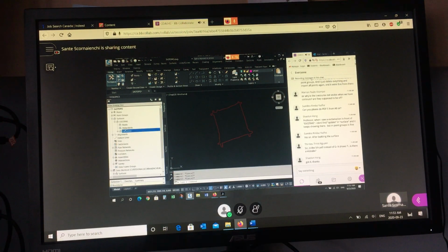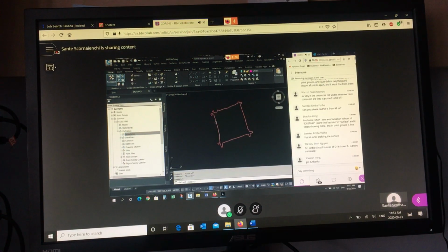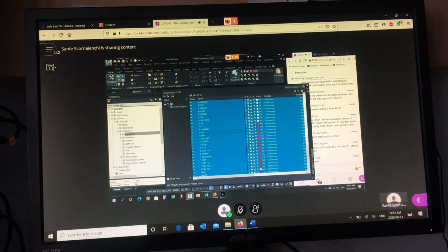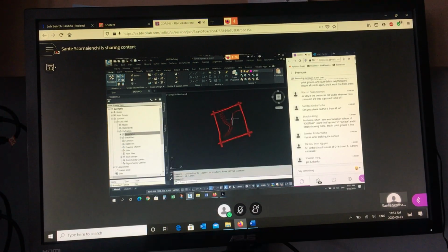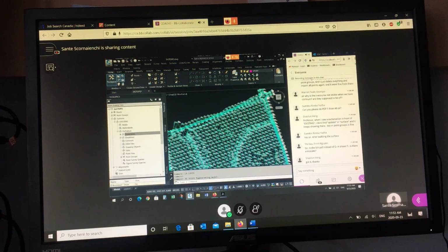And then to define the boundary, you go to boundaries, right click, add. Just accept the defaults, pick it, and it should shrink wrap it. Then I turn everything back on, just turn on all my layers. Regen if you don't see anything. And there's the surface, and it's got a nice clean edge. It doesn't have anything sticking out, right?